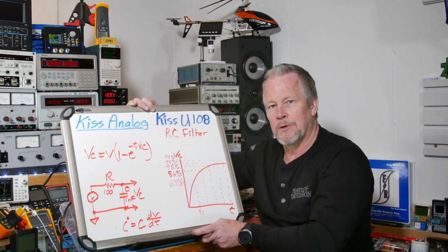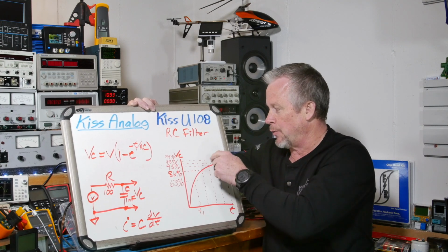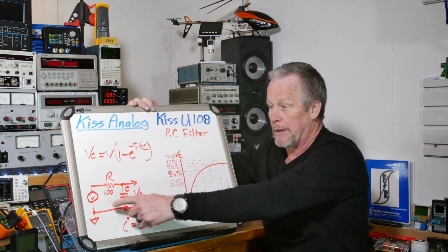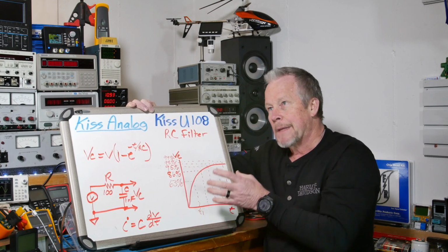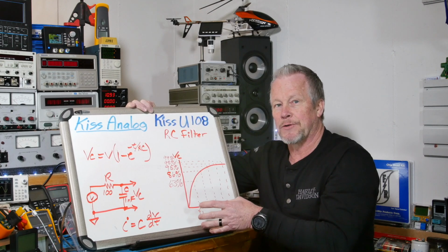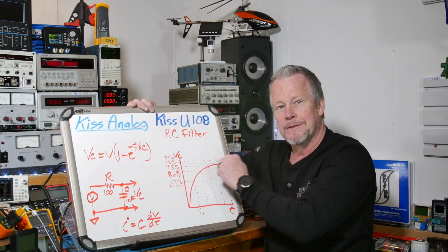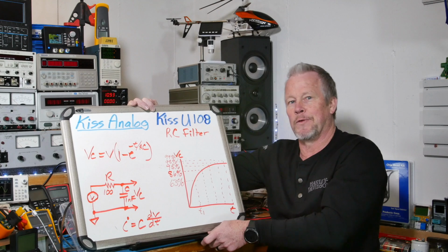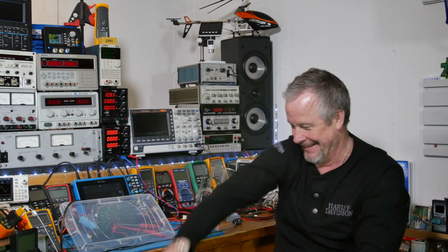Just before we go look at that, what I want to go back to is, let's say that square wave. This was a square wave, and we are going to put a pulse over here. Well, if you had some noise on the front end of that square wave and you just wanted to filter that, you see how you could do that? All you have to do is smooth it off. Okay? There's a clue for what we're going to get to in the next board.